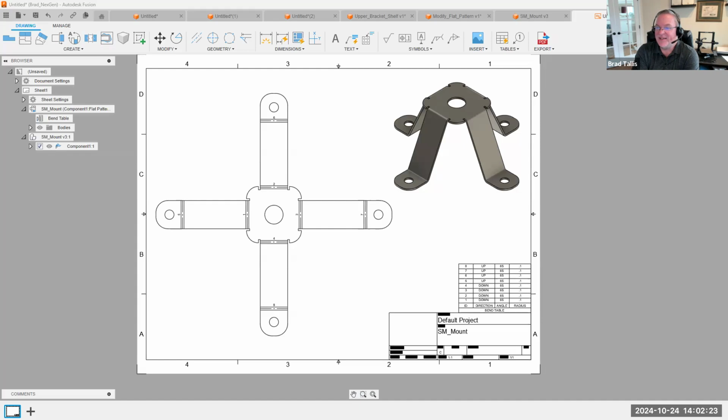I would probably do some testing and see which fibers get crushed, which fibers get stretched, and then measure and get an average percentage there. But like I said, most of the materials out there are around 44%. It's usually in the 40s, which is typically the default K factor. Obviously, that's different for cardboard or polycarb and stuff like that. But I don't have an answer for you for wood.